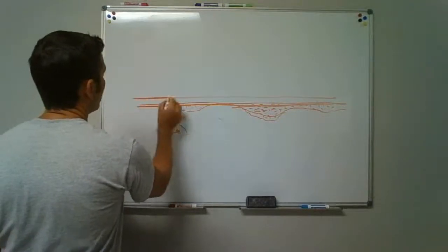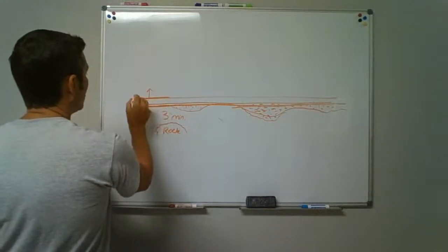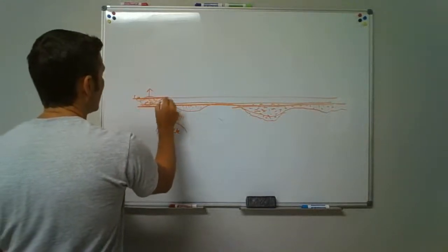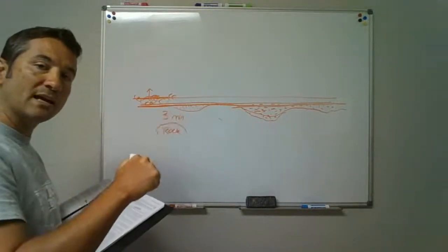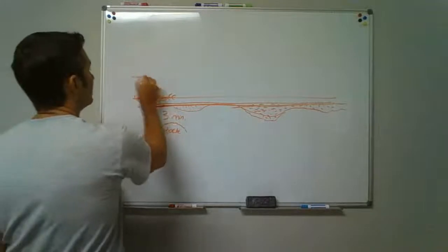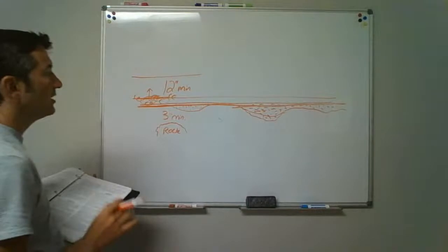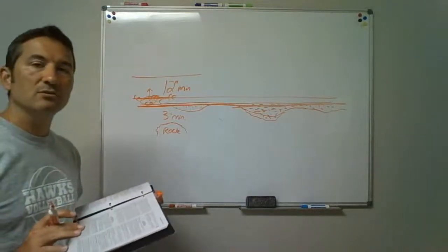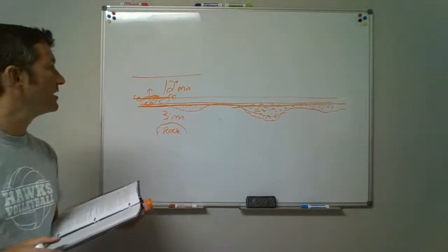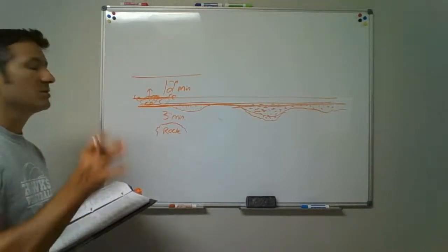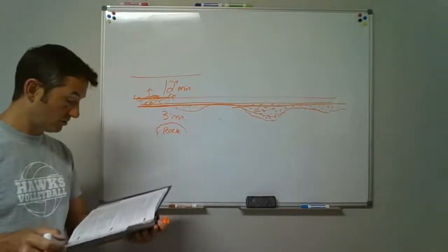The crown's the top edge of the pipe. We've got to go up from that. You're going to fill dirt in here around the sides and on up. Maximum 6 inches layer, kind of packing it as you go until you get at least 12 inches up on top of there. With it all free from construction materials, rocks, chunks of masonry, some brick and stuff like that might be in there. Then you can start to dump some of the stuff on top, because now you got this nice cushion layer of 12 inches of good dirt up on top of it.